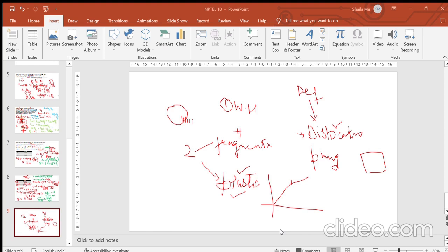I don't know what you mean by vacancy density. But a vacancy is a three-dimensional defect, while a dislocation is not a three-dimensional defect. So yes, both of them are defects. Vacancy concentration is different from dislocation, because a vacancy is a three-dimensional defect, while a dislocation is a linear defect.